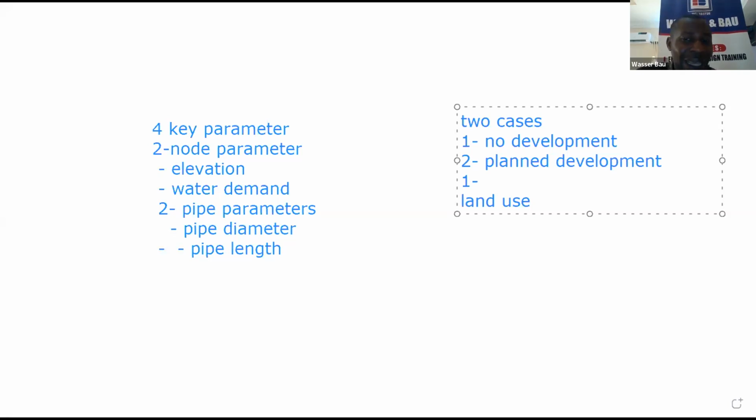Schools is like 10 liters. We don't assign more than 10 liters for schools because it's just for you to go to the toilet, ease yourself, wash your hands, flush the toilet. Nobody takes their bath, nobody washes their clothes, nobody does the cooking, nobody even washes cars. In fact, sometimes they don't even have gardens to water. Their water demand is low. So you now discretize these things, take your time and state them, who has what, who needs what.